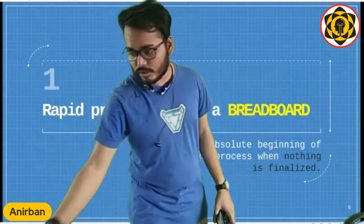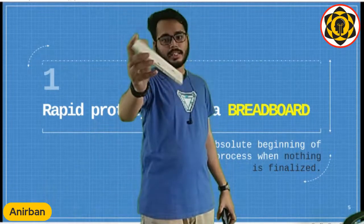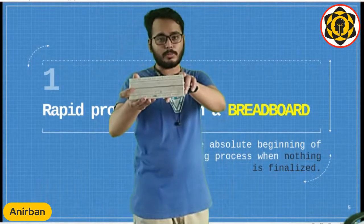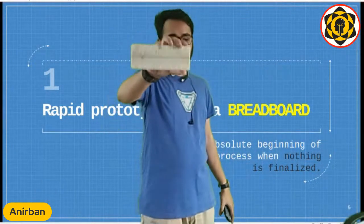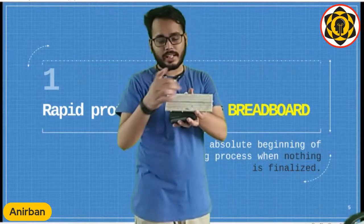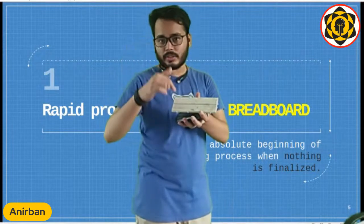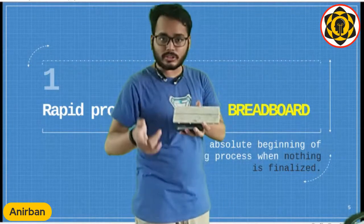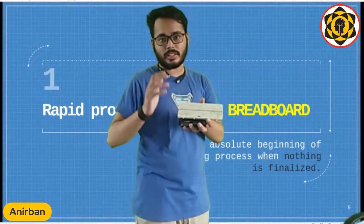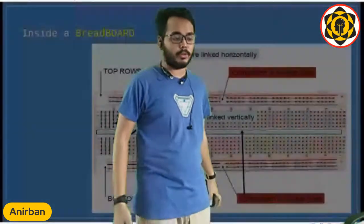A breadboard usually looks like this. This is a full-size breadboard. It can be smaller, like a half breadboard, or a very small micro breadboard, which is around this small. But the full-size breadboard looks like this. And this breadboard has a very interesting interconnected structure, which means that if you connect one point on this breadboard, you can have extensions of that point, multiple points branching out from that point, all electrically shorted. So let's see that interesting structure I am talking about.